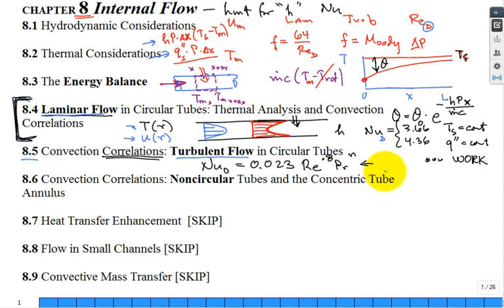And if you have in your mind that Moody diagram, it's not for the entire range of all Reynolds numbers going out to high Reynolds number. It's in that sweet spot where we just have a lot of engineering applications. You know, it's turbulent, so it's greater than 2,300, but it doesn't go up to, I'm trying to remember, I have it on a slide, about 10 to the 5th. Like, what is that, 100,000?